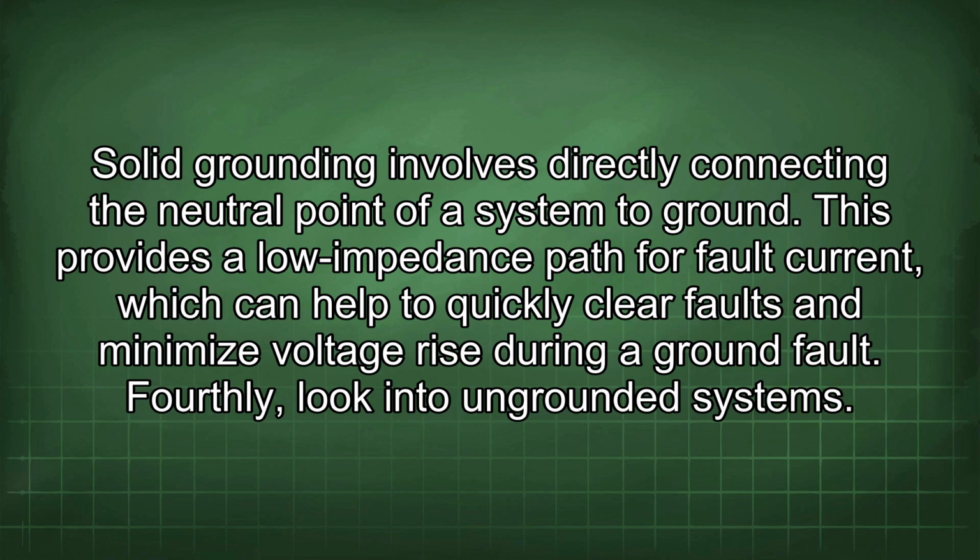Solid grounding involves directly connecting the neutral point of a system to ground. This provides a low impedance path for fault current, which can help to quickly clear faults and minimize voltage rise during a ground fault. Fourthly, look into ungrounded systems.